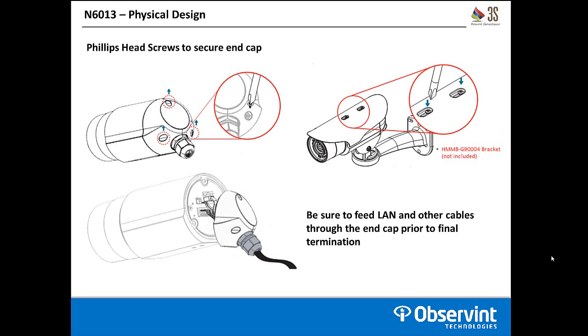The reason for that is a lot of people will put the camera up there, they'll put the connections to the back of it, and then they forget that they have to put the end cap back on, and you can't fit that over terminated cable ends. So make sure you're doing that in the proper sequence.